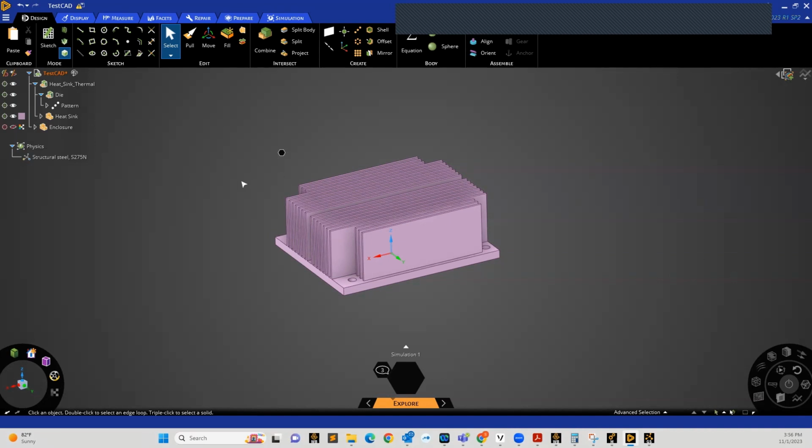So getting started with Discovery here, we've got our CAD model imported. This is just, again, our basic solid model. And now we want to determine how we can go about parameterizing this. Now, from a CAD perspective, the things that we're going to parameterize at this stage are what we call geometrical input parameters, right? So in other words, what we're going to be doing is changing the geometrical parameters associated with this CAD model.